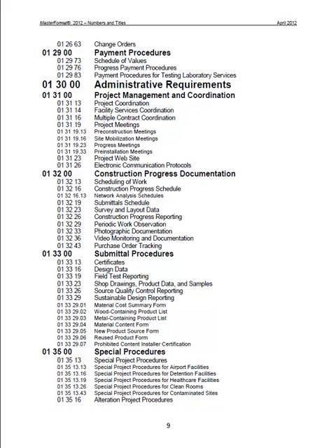The stamp generally says approved, approved as noted, rejected, or revise and resubmit. Those are the options, and any notes would go on a red line drawing back to the contractor to do what needs to be done to make sure that it meets specification.